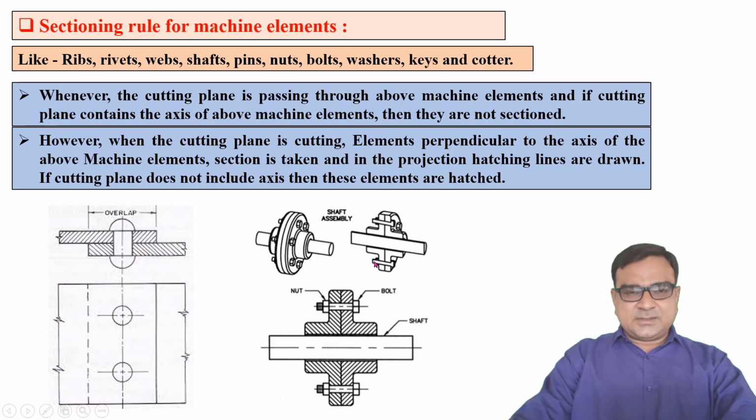This is the top. Now similarly, in one coupling to connect the shaft, when we cut the object with the cutting plane, the front view, meaning the sectional front view, in which this is a shaft, it is not hatched.